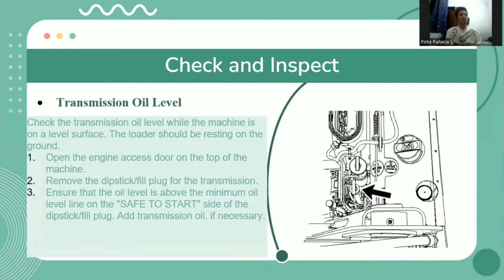The next is transmission oil level. Check the transmission oil level while the machine is on a level surface. The loader should be resting on the ground.